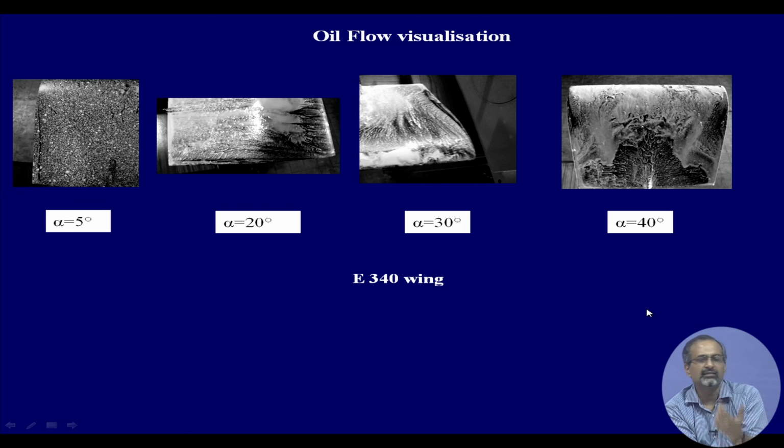We have found that you mount a model into the wind tunnel, you wait for 15 minutes, 20 minutes, half an hour, still things do not stabilize. They keep moving slightly, but on the other hand, it is getting dried up. So, what do you do? You have to strike a balance. Of course, again you have to play with the humidity which is there on that particular day, and here at Kharagpur we can have a whole lot of variation.